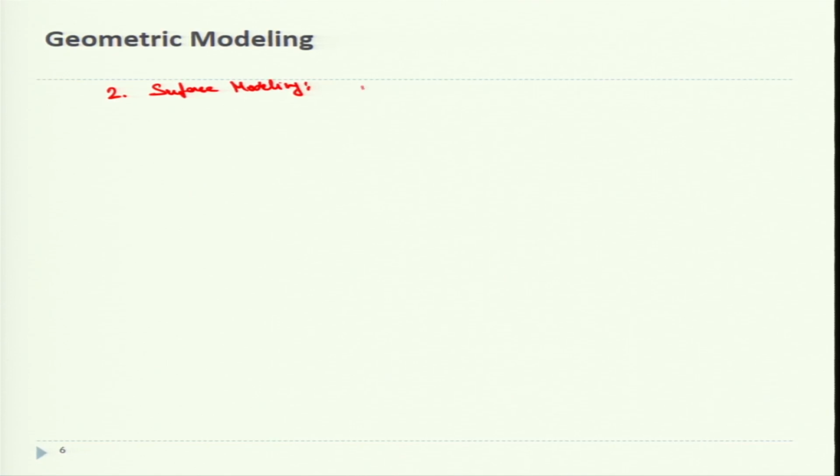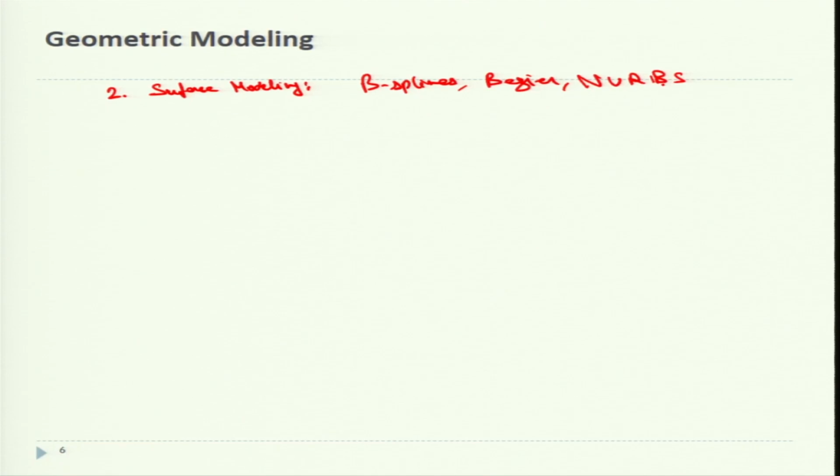So the curves which I mentioned before, B-splines or Bezier or NURBS, which are also B-splines, allow the computer to translate commands into mathematical models. I showed you the mathematical coordinates because the arcs are converted into mathematical models, which are taken as codes known as G or M codes in part programming. These are taken by the computer and mathematical models are made out of them. These models are stored in files and are always available for editing or analysis at any point when we require.